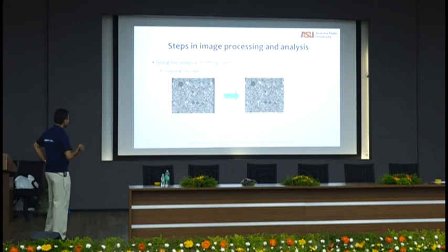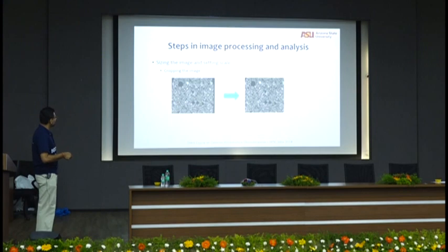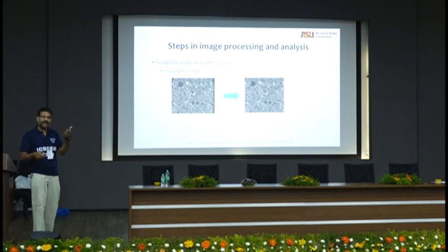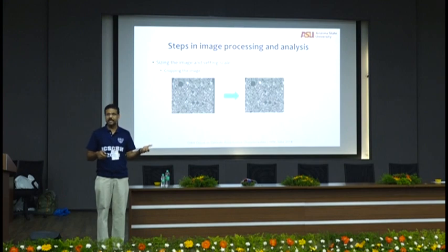Okay, sizing the image. You have to crop the image and make sure it has the right size that you need. You have to have a representative size. So if you have a big fly ash particle here, this becomes a non-representative image, right? The size of any feature in your image should be less than 10 to 15 times the size of the image, as a rule of thumb.